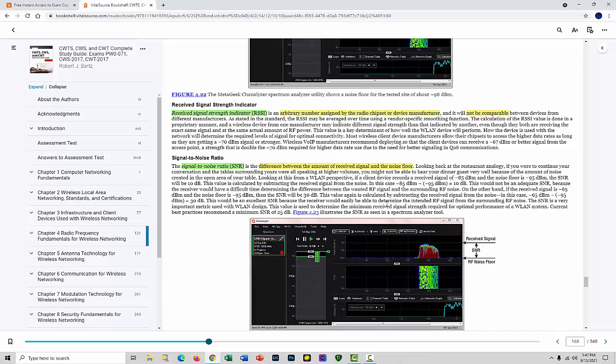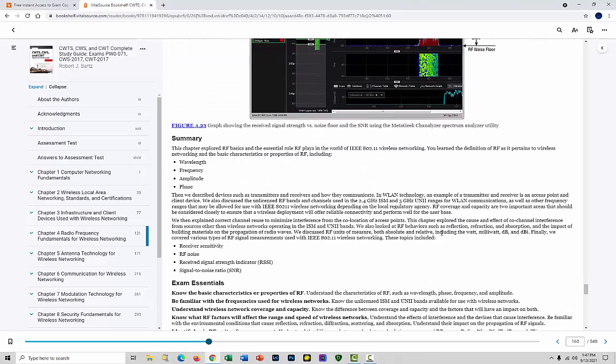So this is saying here, I didn't highlight it, but they're saying that the negative dBm, in this case minus 10 dBm, is not adequate. They're saying you need 25 dBm separation between, this is the noise floor, and this is the signal received. You need that kind of separation in that measurement. And once you know that with the software and hardware you're using, you're not worried about how to calculate those numbers. You're looking to see. In this case, VoIP wants negative 67. That's a higher signal strength than negative 75 dBm, surprisingly enough.